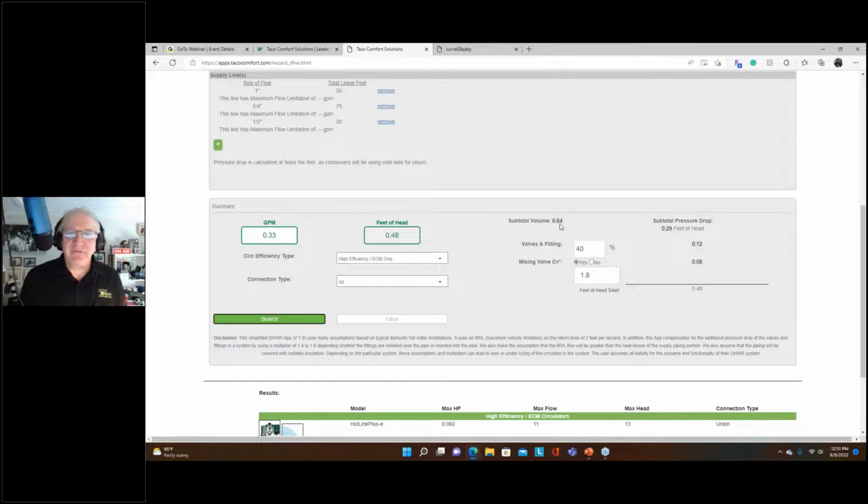At 5 minutes on at that flow rate, if that valve is open, we're going to need to have that thing run a couple of cycles before we get that hot water all the way to that last fixture. All right, so it's going to take a couple of cycles, 5 minutes on, 10 minutes off, 5 minutes on, 10 minutes off.